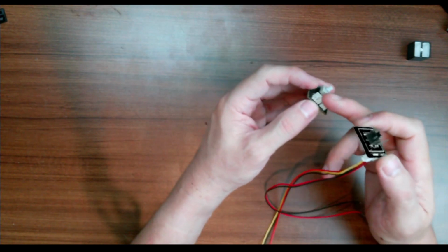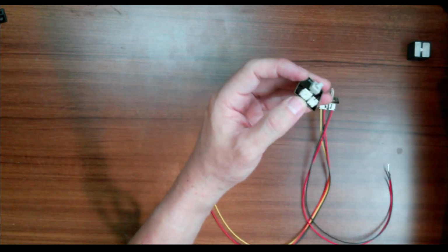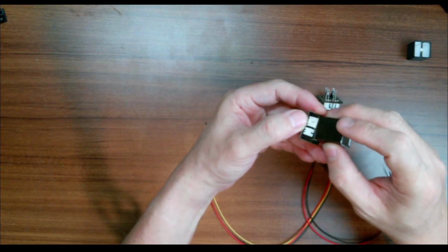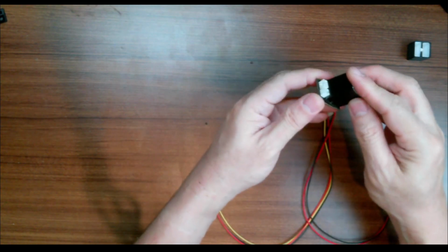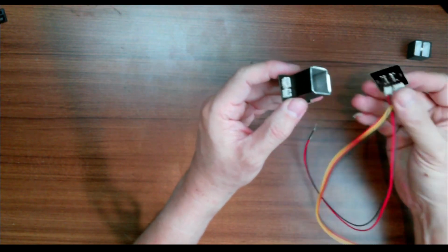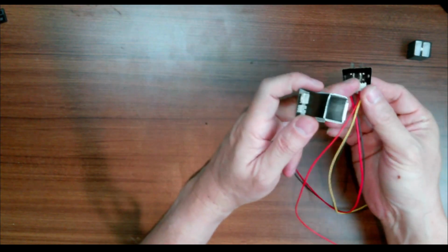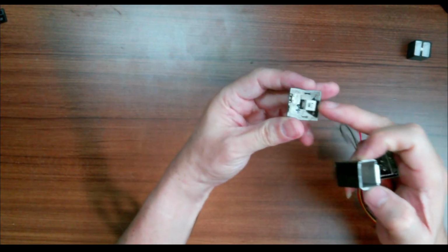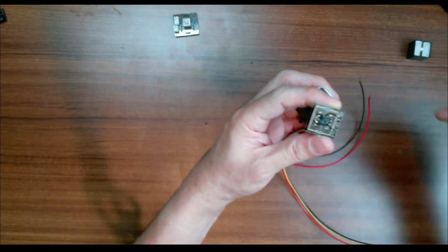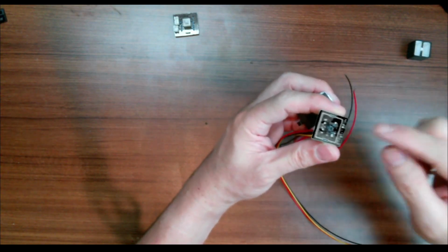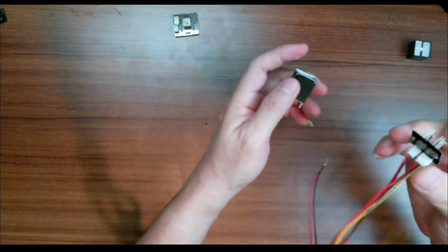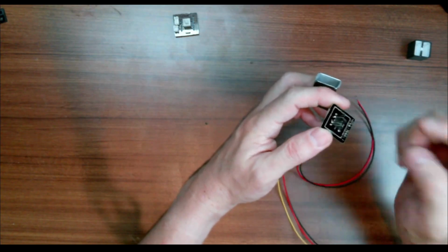So the cable initially goes up like this in the side of the casing, so it's very difficult to install, especially when you are installing it to the panels. Also the third version does not have any resistor anymore. Initially the resistor is put here in the PCB, but in the third version the resistor is moved into the LED driver board outside this PCB. So the PCB is very simple, just the switch and LED.